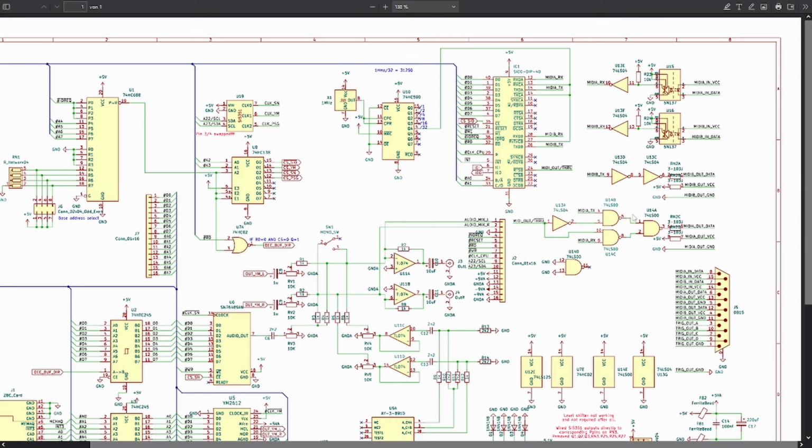One special thing about the MIDI circuit is that port 1 has the ability to have a MIDI through configurable electronically. You can select whether the output of port 1 is the TX pin from the SIO or directly mirrors the input of port 1 MIDI in, this one right here. This is useful when you want to daisy chain multiple instruments, and when, for example, reading this and then resending it via CPU would add too much latency.